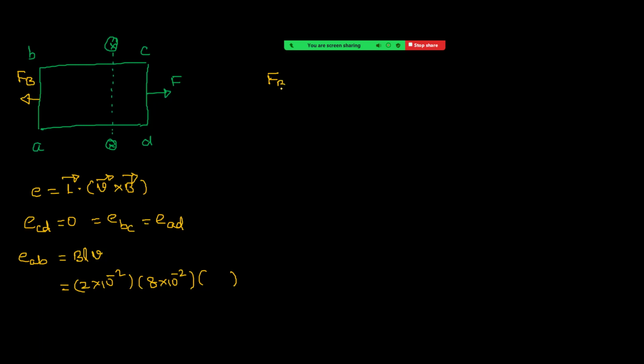That magnetic force is equal to I into L bar cross B bar. So here between L bar and B bar the angle is 90. So the modulus value is ILB. And what is the I value? I value is now E by R. R value given, right? See how much R value given?